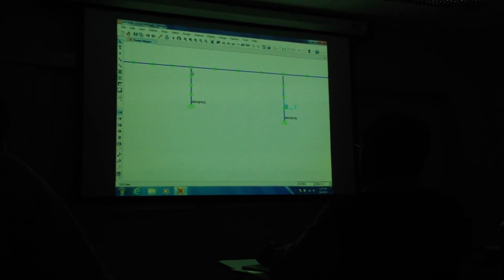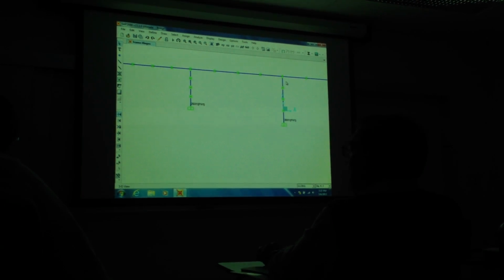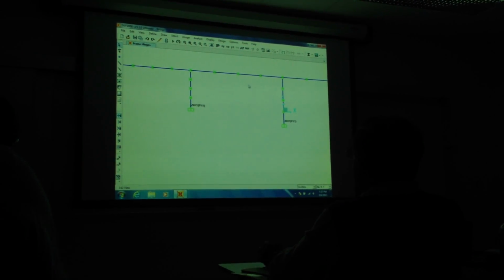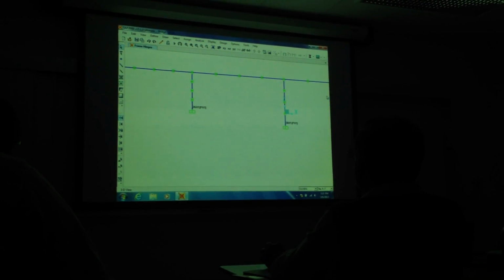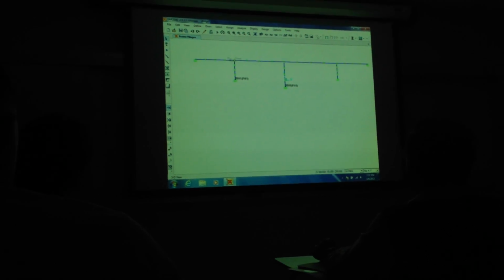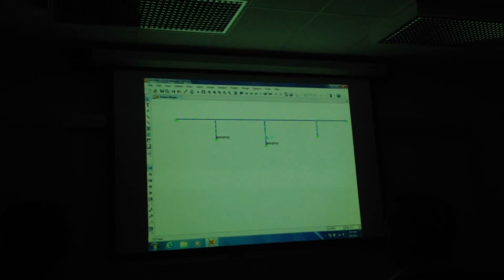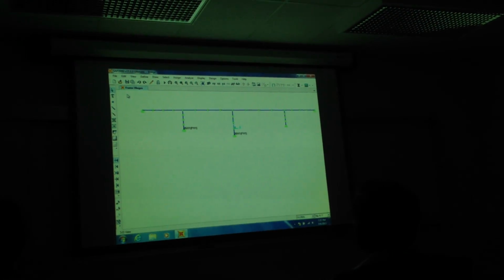Should we do the same at the top? What do you think? Or should we run it and see? Maybe it doesn't need one. Maybe when this forms a hinge, that reduces the amount of moment, that's still okay. Try it this way and see what it is at the top. And then over there, this pin. We shouldn't add too many because, as you'll see, it takes longer to run. And then we'll be standing here twiddling our thumbs.